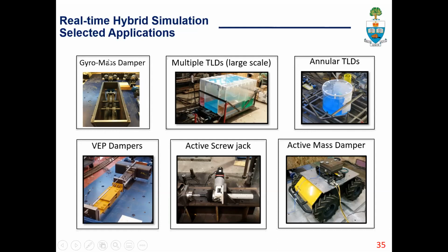It works very similar to a tuned mass damper, but instead of introducing the physical mass, it takes advantage of a gear assembly. Inside this gyro mass damper, there is a set of simple and compound gears. The translational displacements and accelerations introduced to the device get translated into rotation, and the free spinning last gear introduces the inertial force with very little physical mass introduced.